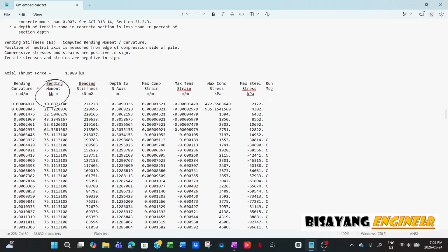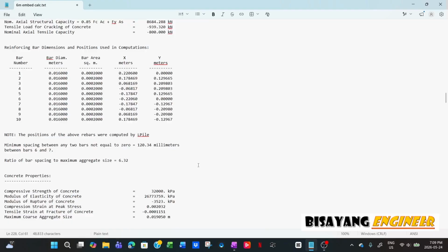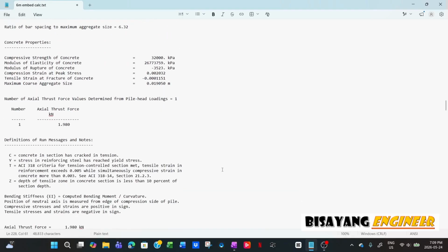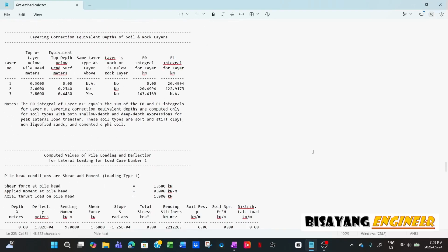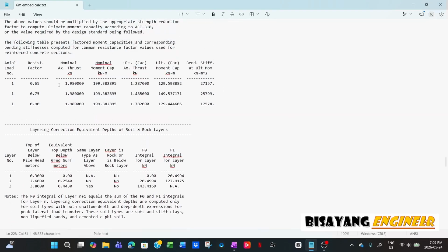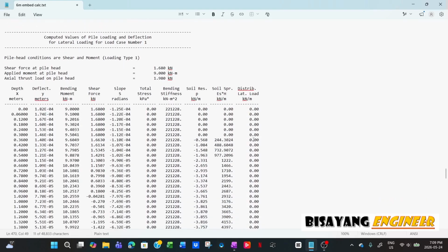So this is at depth. You have bending moment, and the deflection. These are my loads. This one is really small because this is a light post. If you notice, the gravity load is really small, but it's the moment that's critical, the big one.